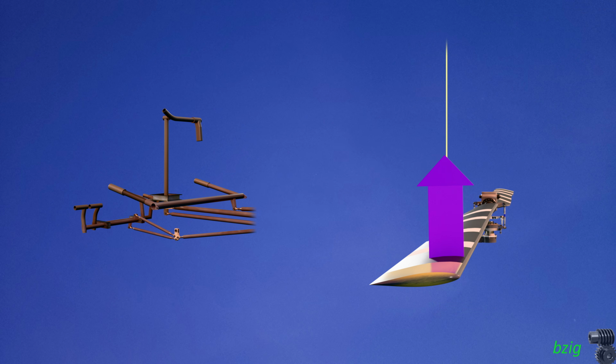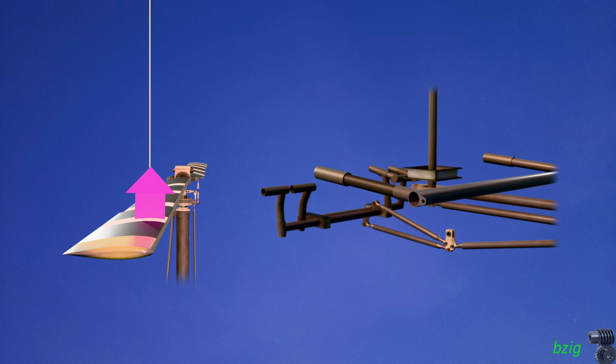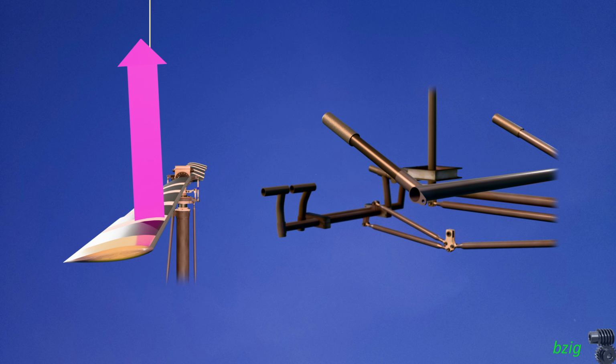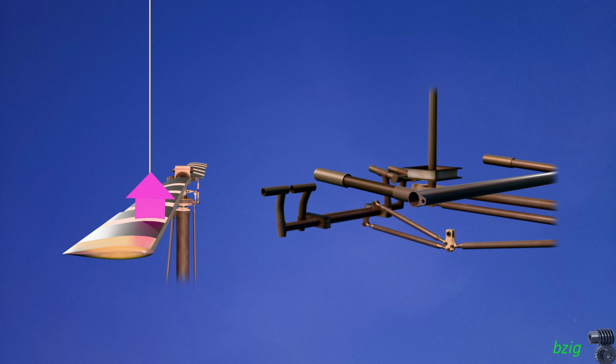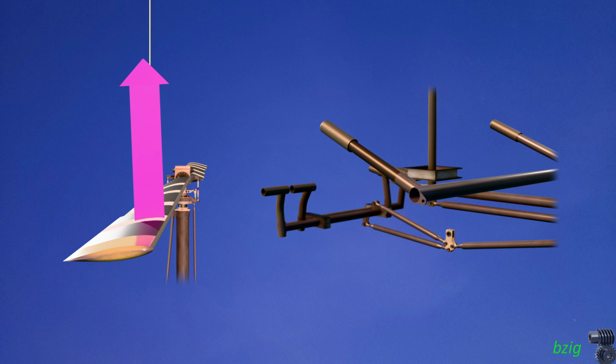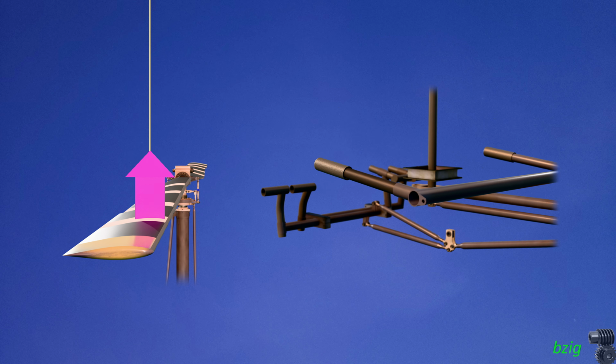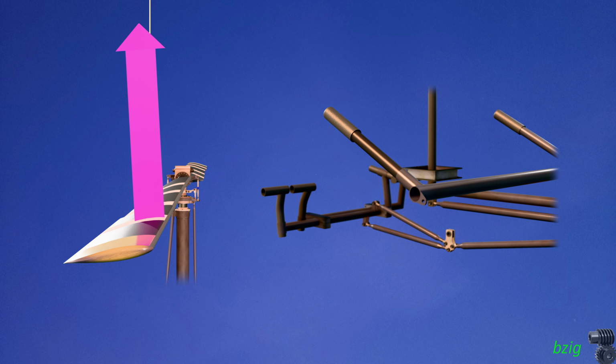We call this a net aerodynamic force because it has both horizontal and vertical components. The vertical component is lift and the horizontal component is drag. By switching to this side-on view, you can see the vector tilt as I raise and lower the collective lever. Tilt is what creates the horizontal component of the force. I'm demonstrating how small this component is in comparison to the vertical component, but that small change has a big impact on how helicopters fly.